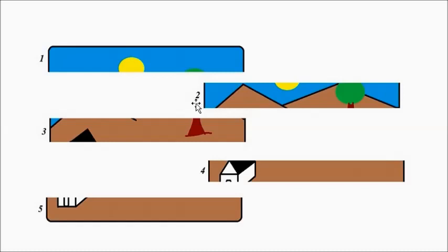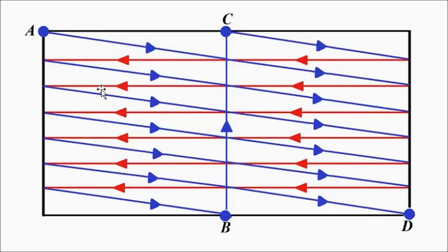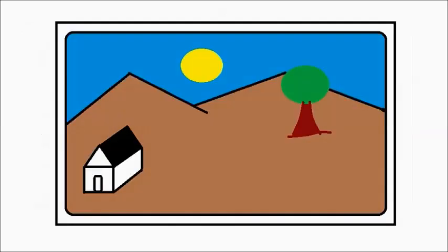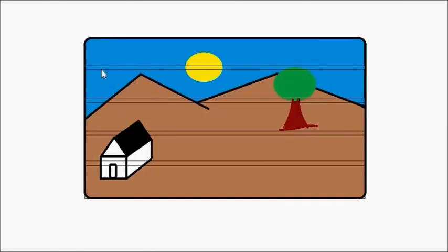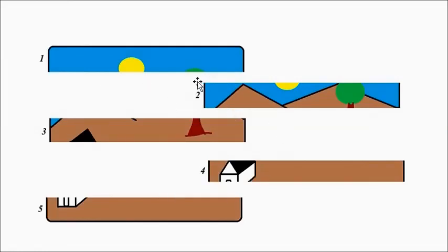So when the scanning takes place, the portions of the odd field and the even field are scanned by the electron beam in portions, and then they are combined together to form the picture frame. But in progressive scanning, the scanning takes place at once. In interlace scanning, the scanning takes place according to the odd and even demarcation of the scanning lines.